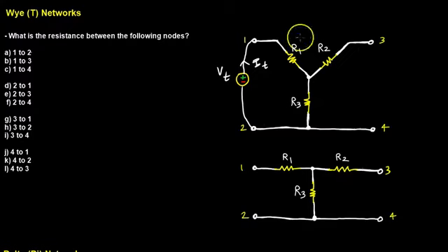Now let's trace this through. What's going to happen? This voltage is applied here. I have a high to low potential developed across these terminals. This current is going to be flowing through some portion of the circuit. But if we look through, we'll see that as it flows through, it's going to take this path. It should be immediately apparent why that's the case, but I'll just tell you: it cannot go through this path because this path does not close around itself. It's not a network, it's an open circuit, and therefore there's going to be no current through it, and therefore no voltage drop across that resistor. Remember, if there's no current through a resistor, there's no voltage drop across it.